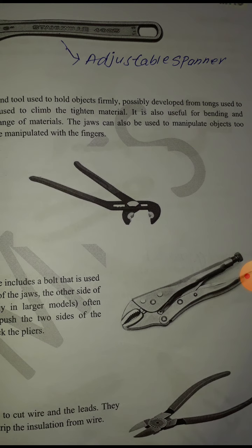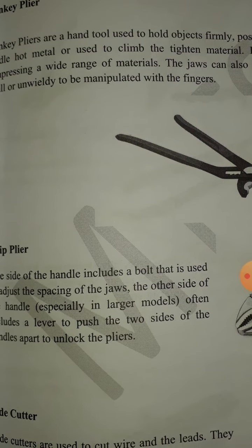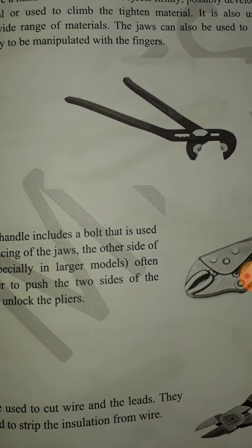They have one good grip, a good catching system. So if you grip this one tightly and it is rounding the threaded rod, this means the threaded rod is not damaged, so it is good to tighten. In many interviews, for cable tray work, they ask which tool to use to tighten threaded rod. That time you can say grip plier for tightening threaded rod. Okay, you can use this one.